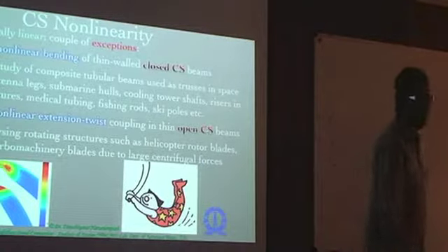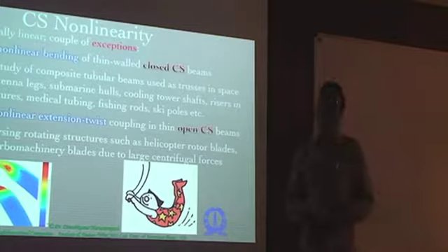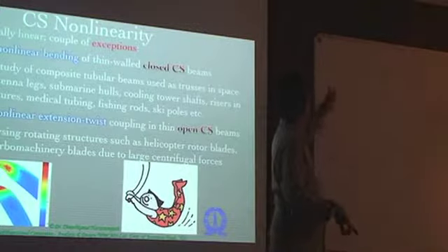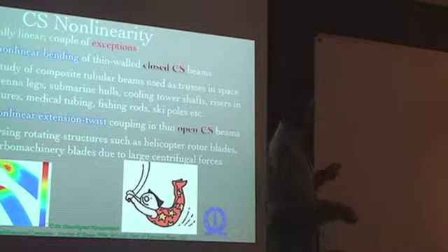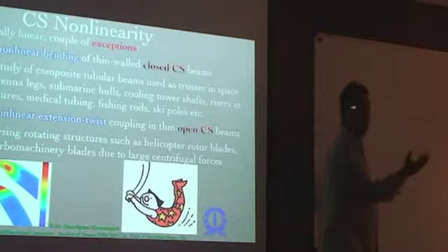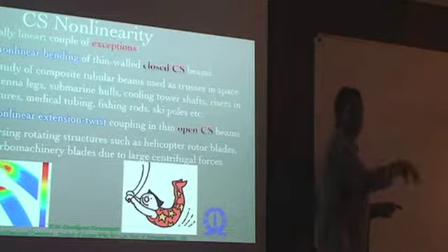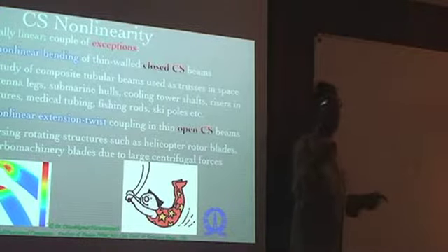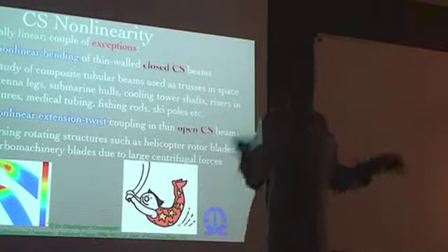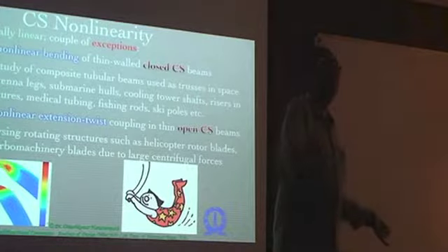So loads don't affect the cross-section analysis at all. They indirectly affect through the gamma 1, kappa 1, kappa 2, kappa 3 because in the nonlinear case especially, your S's are going to depend on them. Okay, so indirectly it will be affecting, but the actual way of applying the loads does not come into picture. It is the effect of that.